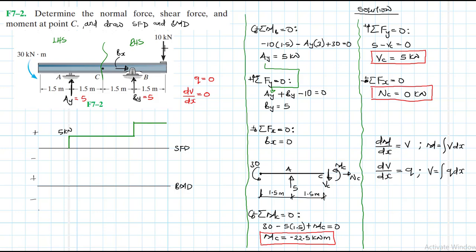And then when it reaches where we have a 10 kilonewtons, again they are going to interact. We have a positive 10, the other one is a negative. So when they add up, then this closes up, right? It will come down to 0, okay? And you expect this. When your diagram doesn't close up, then there's a problem. All right. So there we go. We have this shear diagram, which is all positive.